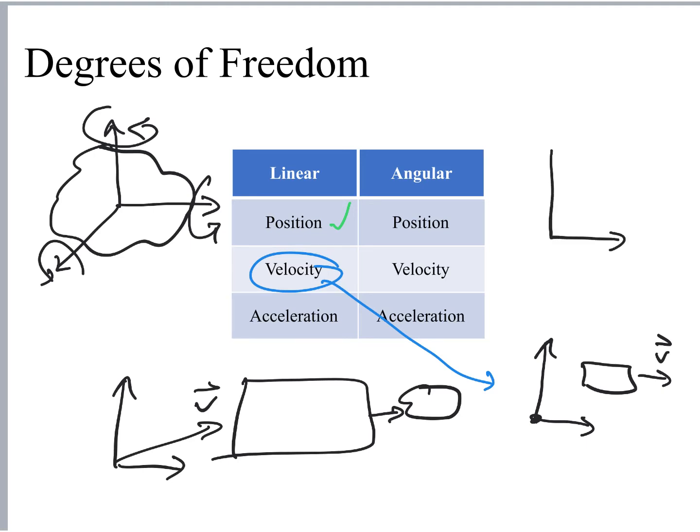So we have an inertial reference frame, and rather than letting an object move, and we'll talk about this on the coming slides, we can measure the acceleration of that object due to the force it exerts on something else. If we allow it to move relative to the reference frame and we apply some sort of spring or other flexible element, we can allow that mass to move, and then we can measure a force. And so this one's a little bit easier than the velocity because it allows us to keep the two parts of the sensor in a relatively small range relative to each other.